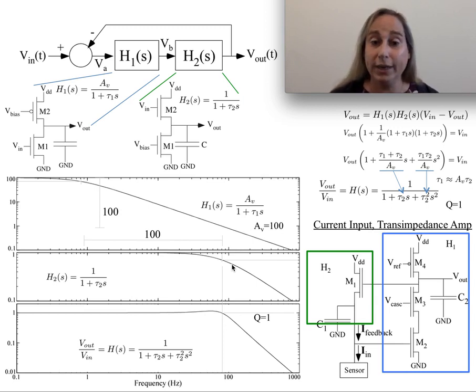And this becomes quite a significant constraint for a number of different circuits, because either it means make something go faster, usually you need a gain of 1, or slow something down, and I have to be very careful of this. Well, if I do this, then I definitely get a nice Q equals 1 type of frequency response over that range, and I can see how everything lines up all the way through, particularly at the gain of 1 equal point, right? Gain of 1 there, there, and there. So again, this is probably a very reasonable response, and depending on your situation, you might be able to tweak it one way or the other.